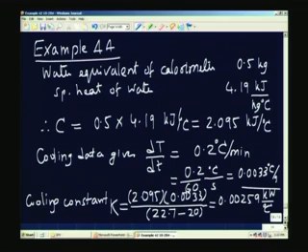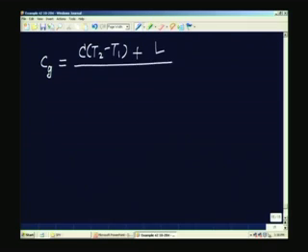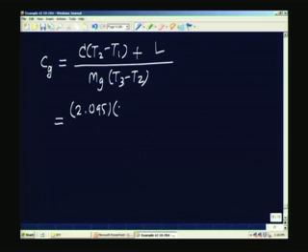Now, all I have to do is use the expression given earlier. C of glass beads must be equal to C into (T2 minus T1), this is the expression which we had written down earlier, plus loss, divided by the mass of the glass beads multiplied by (33 minus T2). So, capital C is 2.095, T2 is 22.7 minus 20, plus the loss, which is nothing but K into that integral.